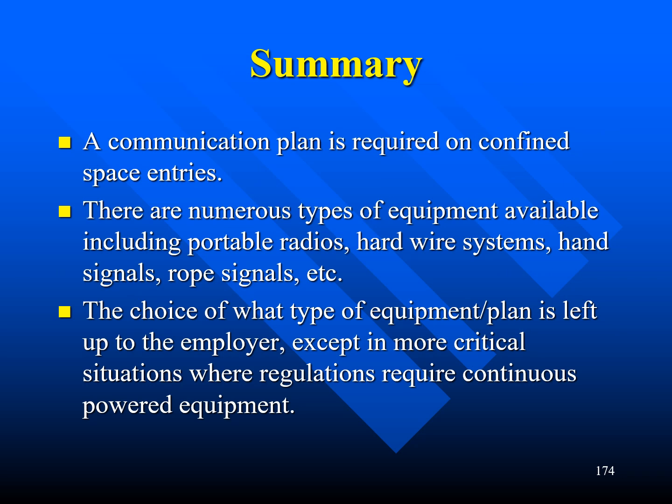Let's summarize this lesson. A communication plan is required on confined space entries. There are numerous types of equipment available, including portable radios, hardwire systems, hand signals, rope signals, etc. The choice of what type of equipment plan is left up to the employer, except in more critical situations where regulations require continuous powered equipment.